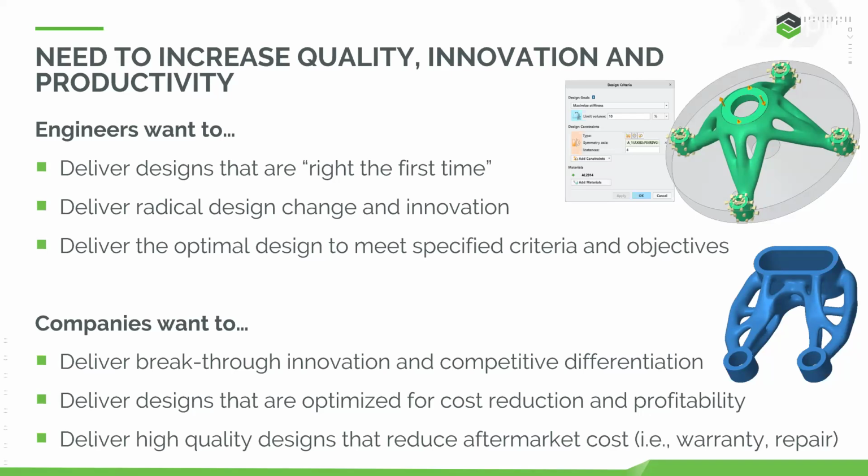So we have the loads, we have the constraints, we have the materials. When it begins to solve for that design study, it knows where there's stress. If there's stress, I need material. In areas of no stress, I don't need material. So now I can start to pursue anything where maybe structural integrity is important and weight reduction is critical.